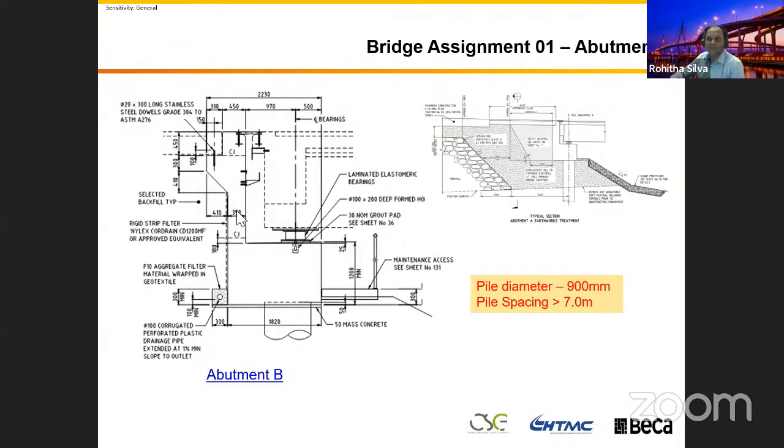These are the things you need to be mindful of, because this dimension comes automatically. And the thickness of this member is mainly governed not only by the sizes, it's the 4 layers of rebar plus the concrete, 4 layers of reinforcement plus the concrete cover, front and back.